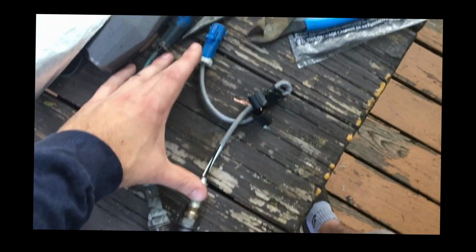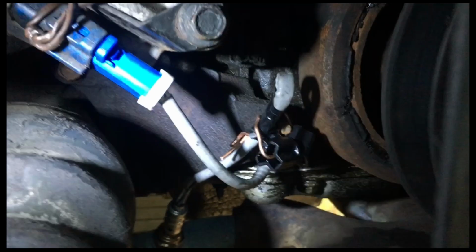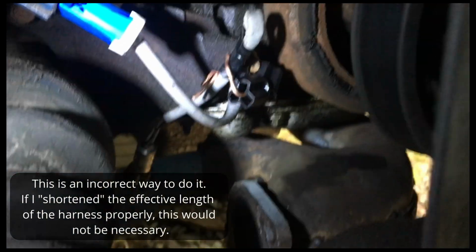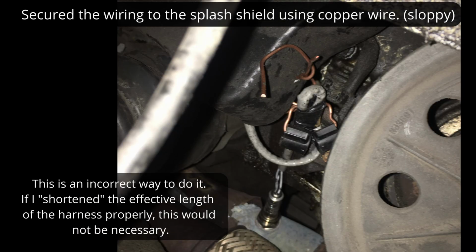But going back to the issue of slack in the wiring, if there is too much slack, it could potentially rub into a hot exhaust or rotating components like the crank pulley dampener or the CV output shaft here. This particular O2 sensor's connector is between those two rotating components, the CV output shaft and the crank dampener. So that's just something to take note of. The way I did it here is sloppy, but I will redo this at a later date.